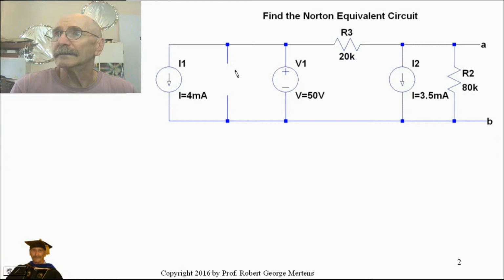The next step is what? What are we going to do here? I think the only thing we really can do is take this voltage source and convert it into a current source. We have a resistor here, and if we do that, we can get this thing out of the way and turn this into a whole parallel circuit. So this calculation is going to be figuring out what this current source is.